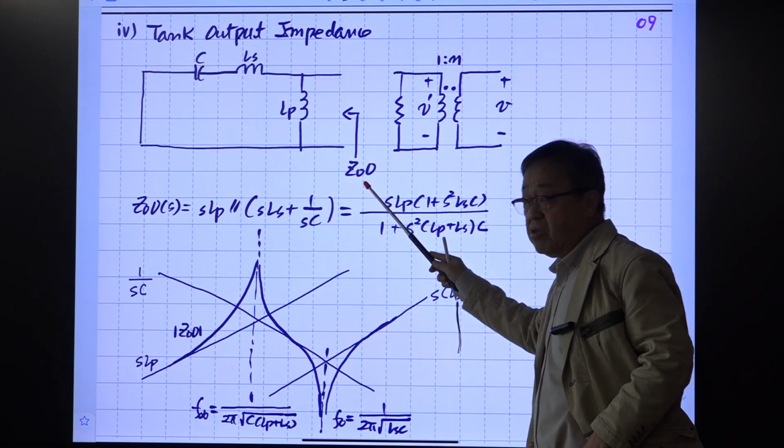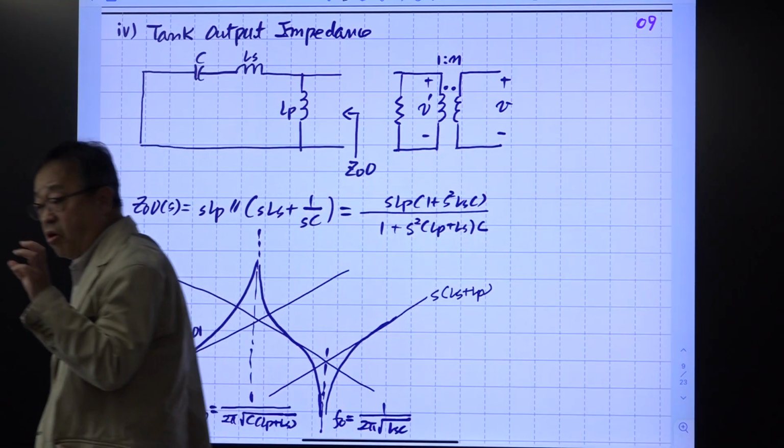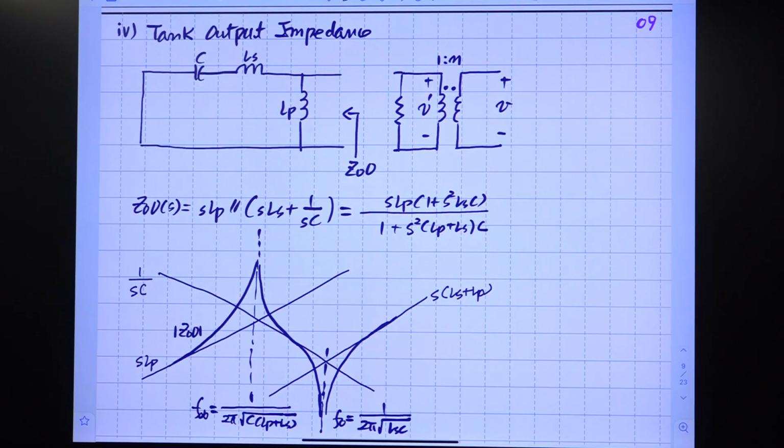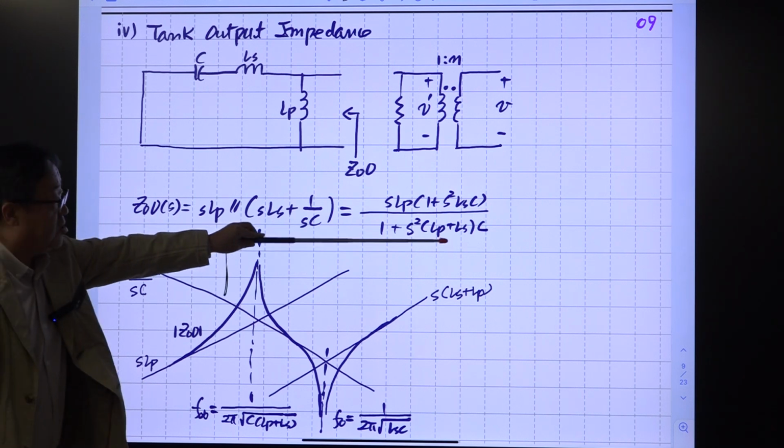This occurs as one critical circuit component in Thevenin's equivalent circuit. Output resistance with the input port shorted is very critical information in designing the tank circuit and in predicting the performance of your converter. So this is the expression, and this is the expression.